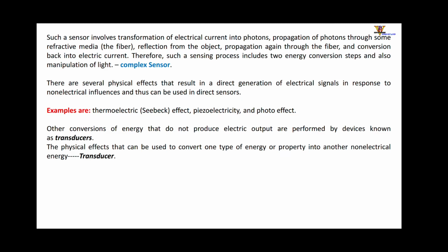Piezoelectric crystal uses pressure or force applied on piezoelectric material, and then that will generate a corresponding voltage across the piezoelectric crystal. The same with the photo effect, as in a photodiode, where photons bombard the photodiode, and then it will generate some electric current.